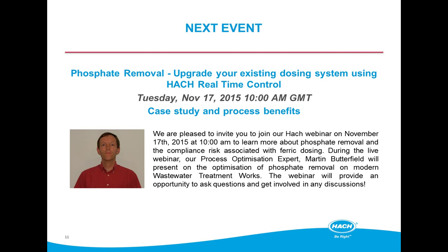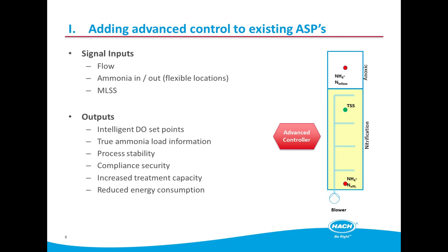So to do that, you need to understand how many workers effectively you have in the aeration basin. The controller will have an understanding of the sludge age. If we look at the slide, let me take me back to the slide here. Because we've got a measurement of the mixed liquor within the aeration basin, that gives you a kilograms of total biology.